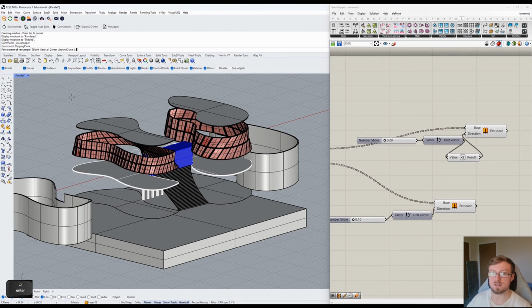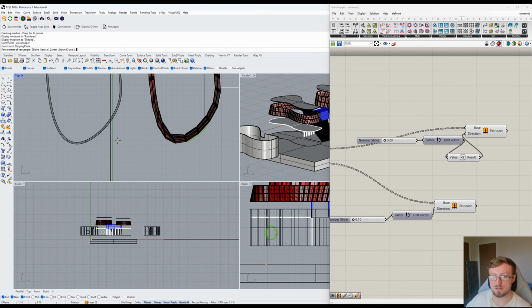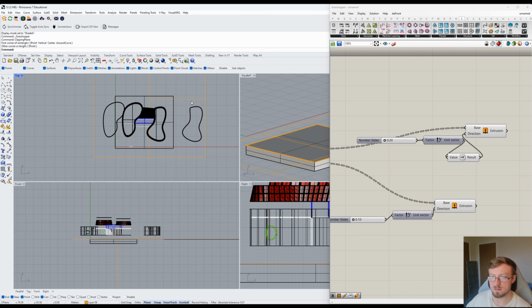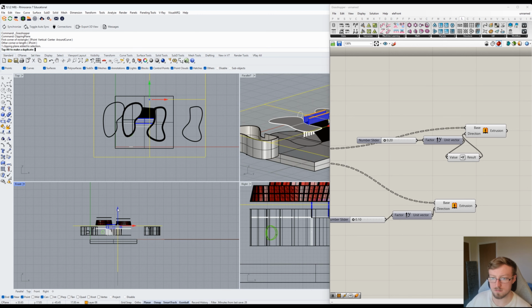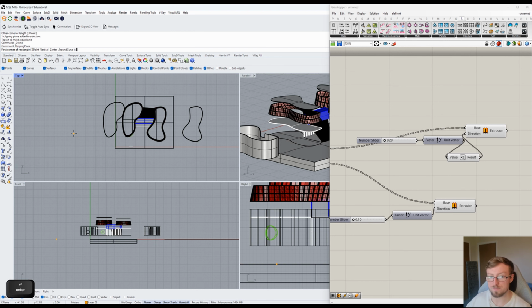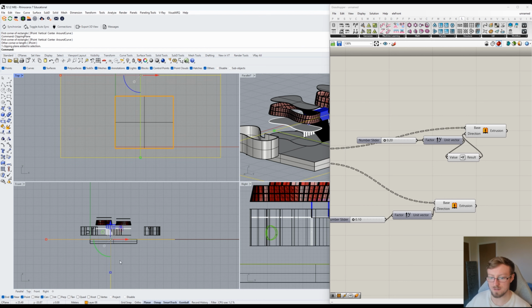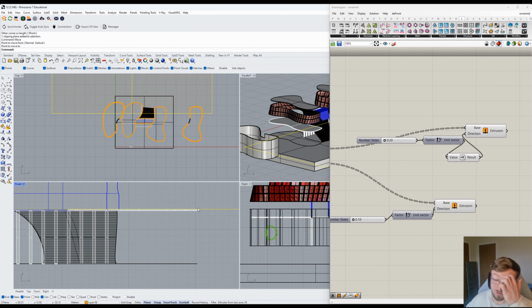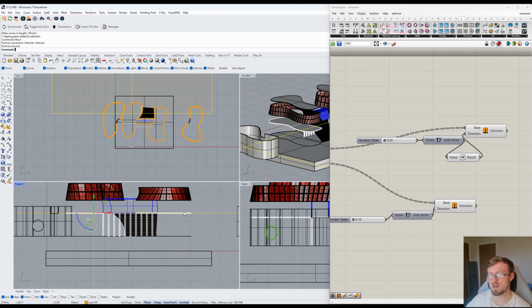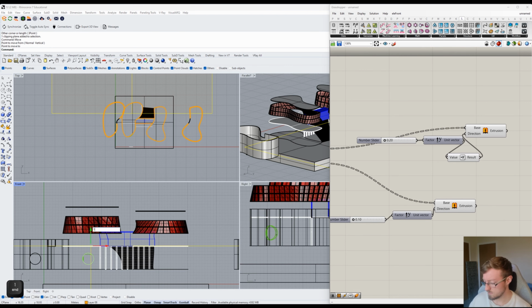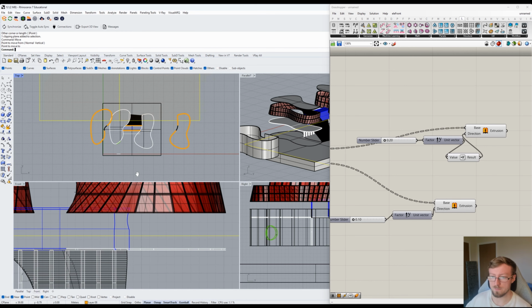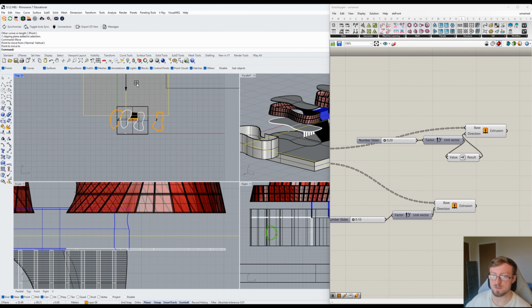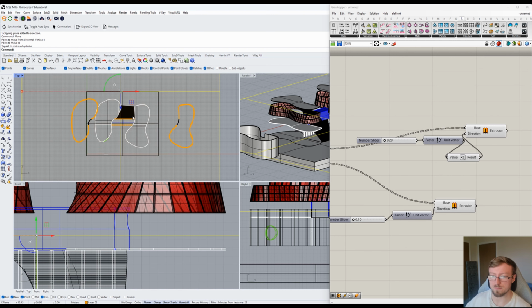Let's just show that. If I get a clipping plane, let's go here and here. Let's try that again. Here to here. There we go. And let's move it to top of here. I think section cuts are taken at 1.5 meters above height, so let's see what that would be there. So you need to see that. You can move this, it doesn't really matter, from the positioning.